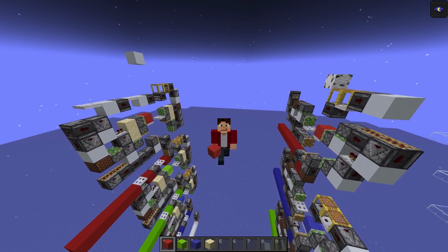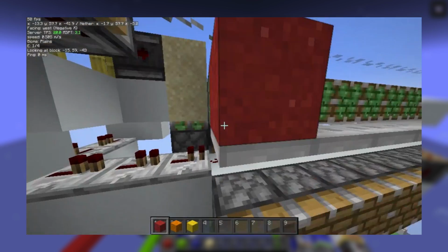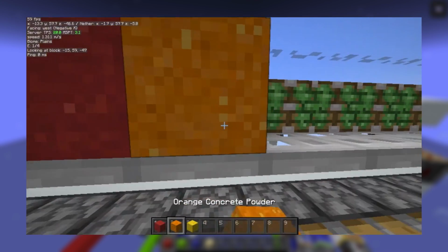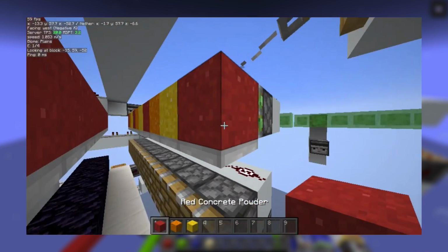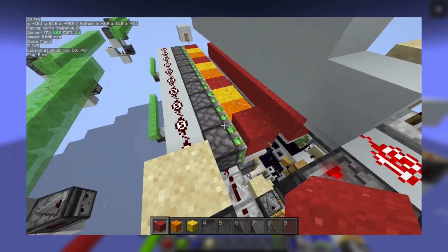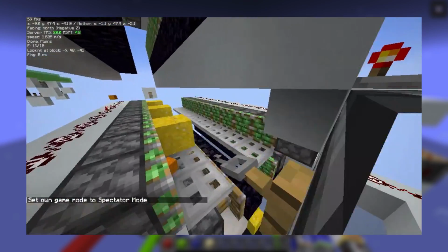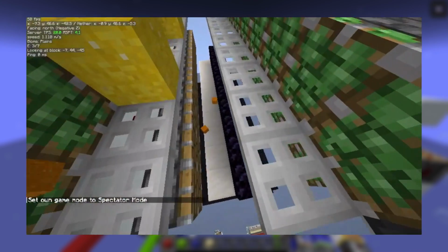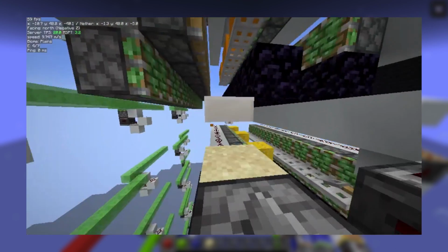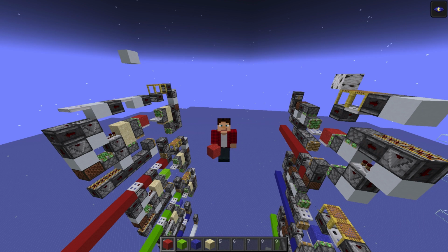So now let's dive into some of the actual designs. Now I am going to exclude some of the iterations that simply didn't work. But for example, with this one, it's important to note why it didn't work. With this one, we're firing multiple pistons all at the same time, no matter if there's a block to sort or not. So some of the time there isn't actually a block that's being sorted, and this is causing the control blocks to fall out because there's no block to push the control block back into position. So overall, this one has some weird functionality because either the control blocks fall out or they get moved to a weird position. And yeah, this is why we need a 1 wide tileable design that doesn't interfere with the slices next to it. So it needs to be independently controlled, unlike this one.